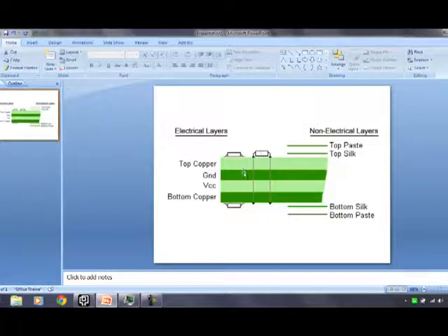could see here in a 4-layer board, and it is literally like a sandwich. We've got the top copper layer, a ground layer, a VCC and a bottom copper. You could actually just put wires to punch down into the ground, into the VCC, to take power locally from the actual ground or power planes.